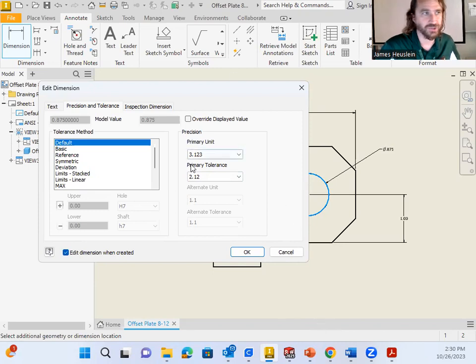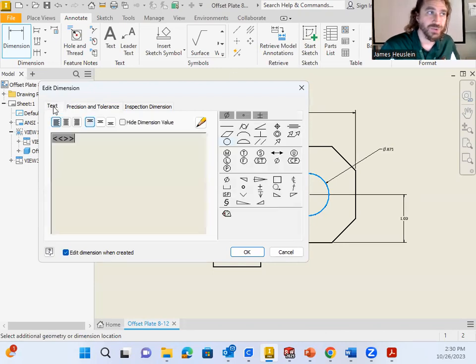Excellent. That looks good. Now, also in the drawing, there's reference information that says this diameter is for 3 holes, that all 3 holes have this diameter. To type in a little notation after a dimension is put in, we go to this text box, the first tab, and then we just type in that message, 3 holes.